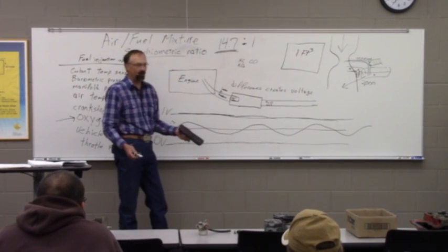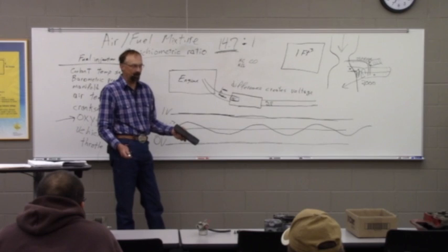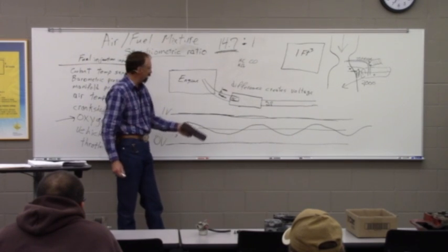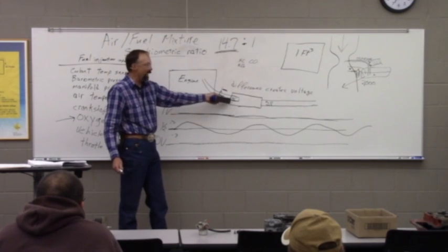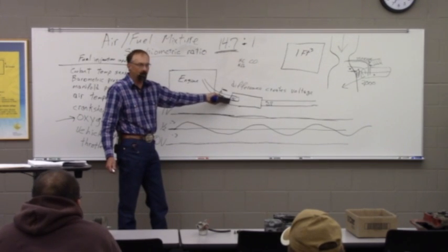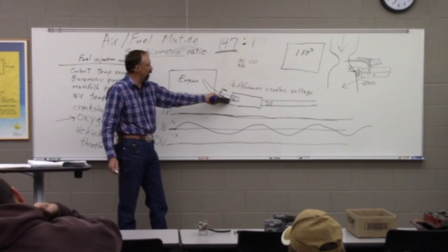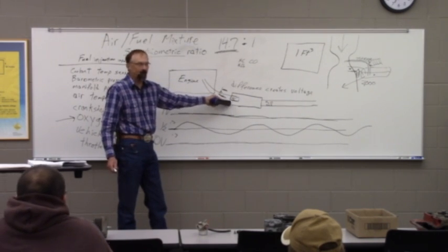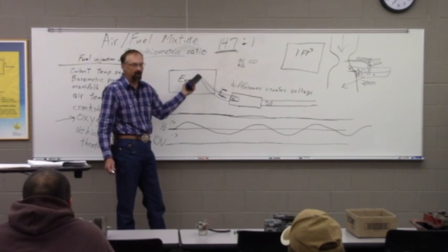Mistakenly, people have thought that that was a malfunctioning catalytic converter. It's actually a catalytic converter doing its job when the fuel mixture's out of whack and it's getting a bunch of raw hydrocarbons shoved in its throat. So in that case, you don't need to look for a new catalytic converter. You need to go look and see why our fuel mixture is out of whack.